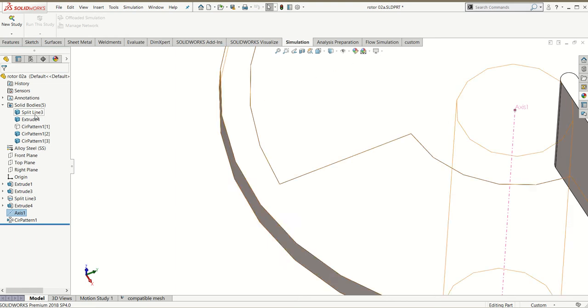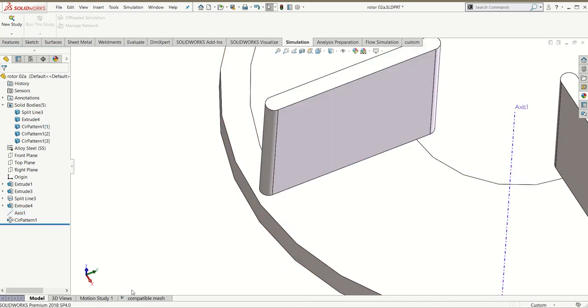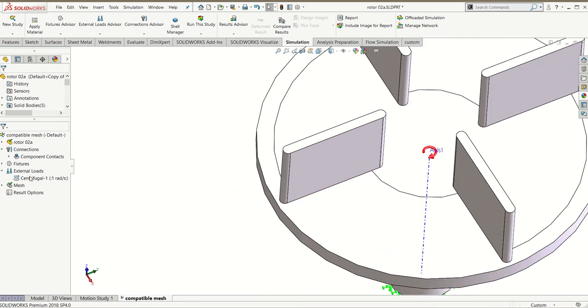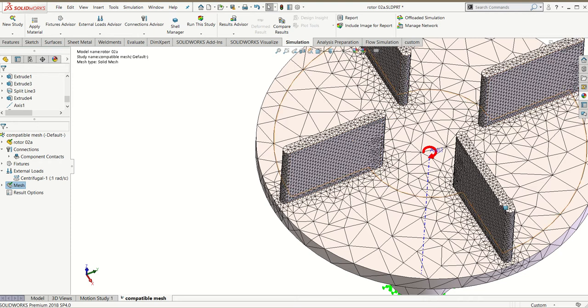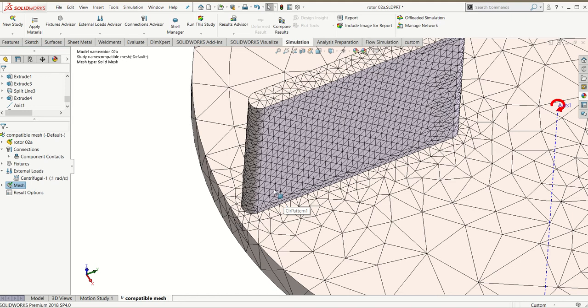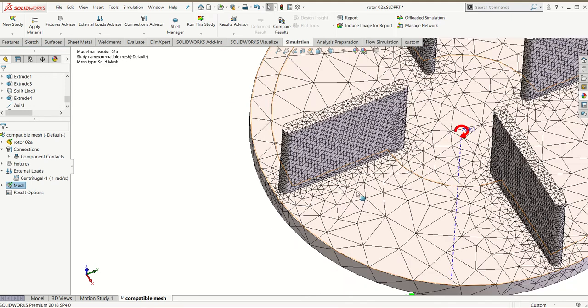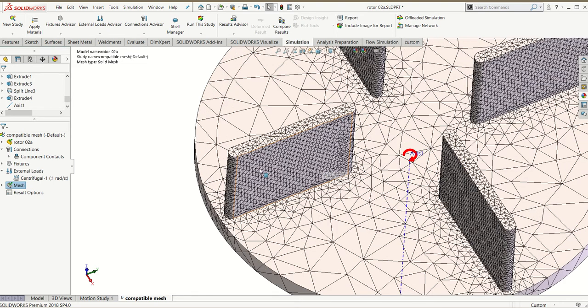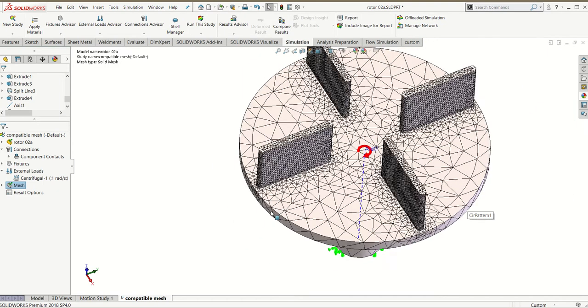So if I go here, if I see, basically, in this case, you can see this is my source. If you go for show mesh, these are my source elements, and these below are my target elements. So load transfer means the calculation is happening between this node and the other node. Due to compatibility, the nodes are matching with each other, and as the bodies are separate, each one has its own nodes separately.